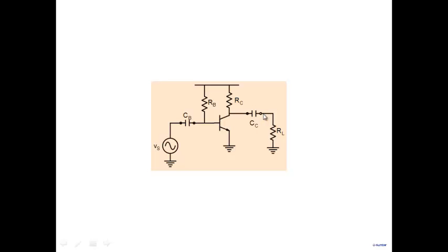One of the problems that we are familiar with is that this particular circuit is very sensitive to beta. The bias current ICQ is determined by the base current. ICQ is beta times IB, and IB is fixed through RB. So although IB does not change because IB is decided by RB and the supply voltage, the ICQ being directly dependent on beta varies with the beta, and therefore everything in the amplifier varies here.